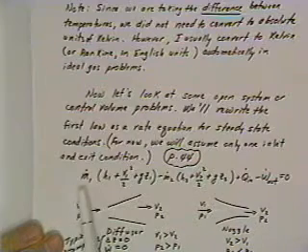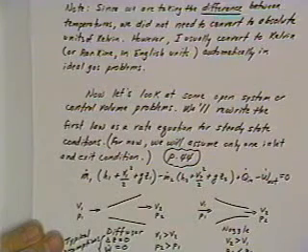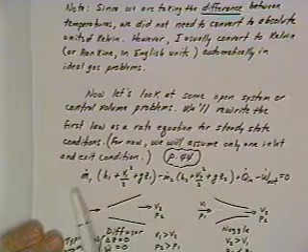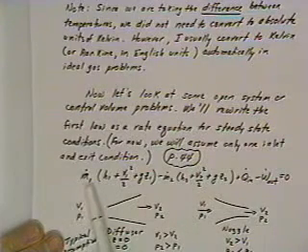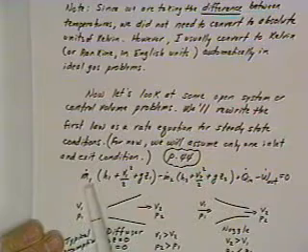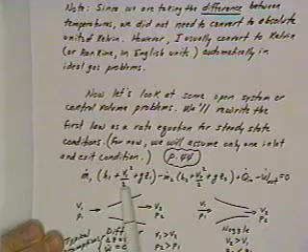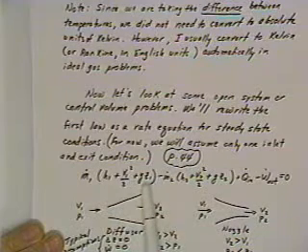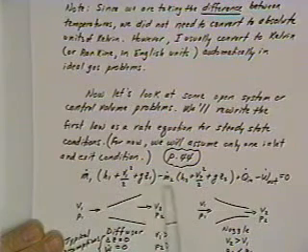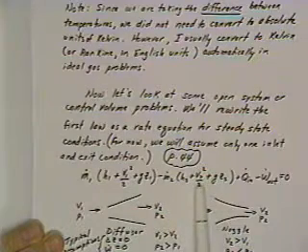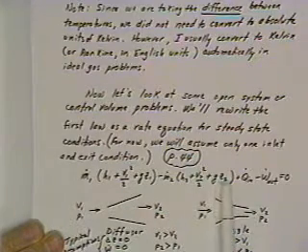So our first law that we had written as an open system or control volume approach from page 44 simplifies to m dot 1, which is the entering mass, multiplied by the enthalpy of 1, plus V1 squared over 2, the kinetic energy term, plus g times z, the potential energy term, minus m dot 2 times H2 plus V2 squared over 2 plus g times z.